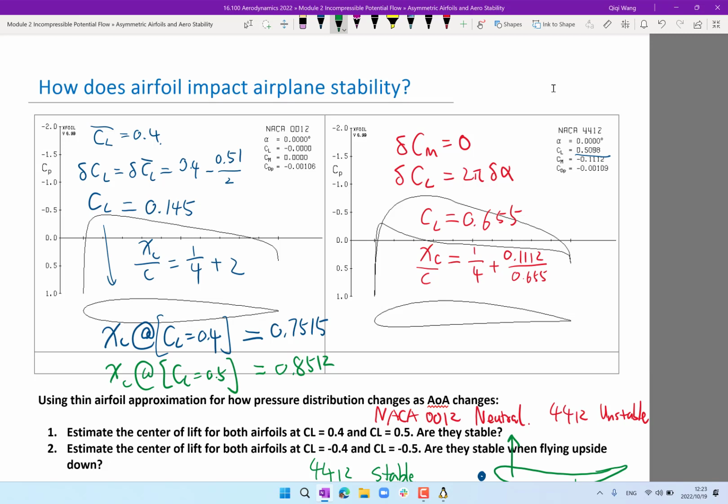A flat plate solution requires a vorticity distribution from here all the way to here, including in the gap. That's not realistic, right? Because in order to simulate the flow around the airfoils, we place sources, sinks and vortices inside the airfoils. These are realistic flows. But if you place vortices in free space, it's not a valid flow solution. Because, remember the vorticity equation, the vortices will be convected downstream. It's not going to be a steady state flow field.